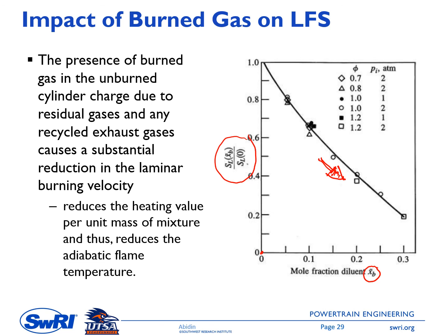The burn gas is used to control NOx. It can also be used to increase gamma. And from the thermal efficiency perspective, you saw that it increases the engine thermal efficiency. You can check in the previous slide that the thermal efficiency of the engine increases with the compression ratio and gamma. But having a higher burn gas will reduce the laminar flame speed significantly. So there is a limit for the EGR, otherwise you will have a misfire inside the engine.